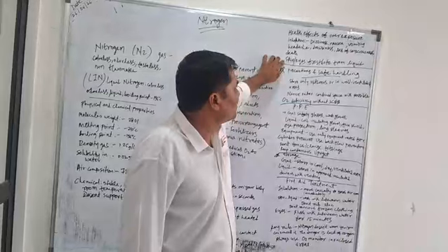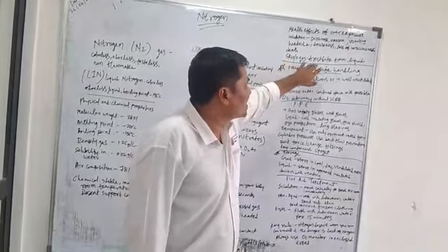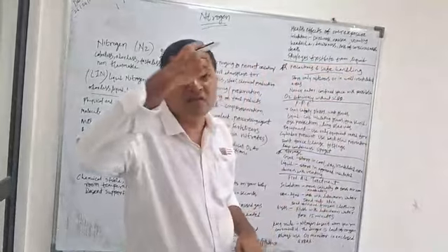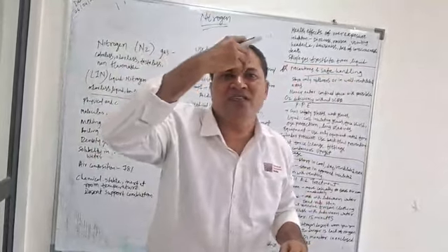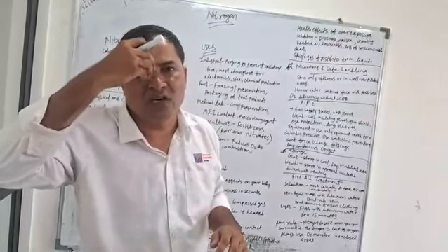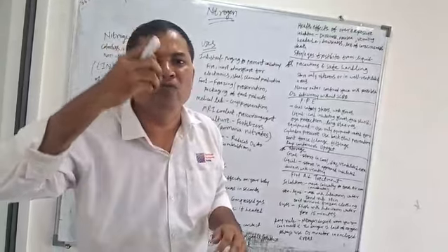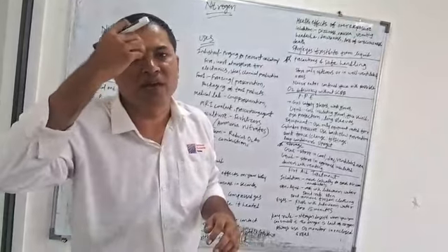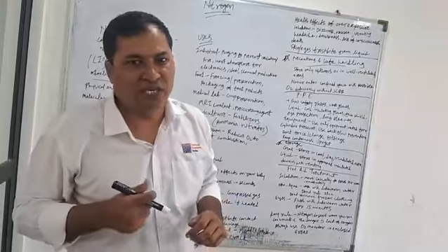Okay, if the skin or eyes come in contact, you may get frostbite from the liquid. If the nitrogen liquid comes into your eyes, you can wash your eyes with lukewarm water. Lukewarm water. Never use cold water. Apply lukewarm water and flush your eyes.